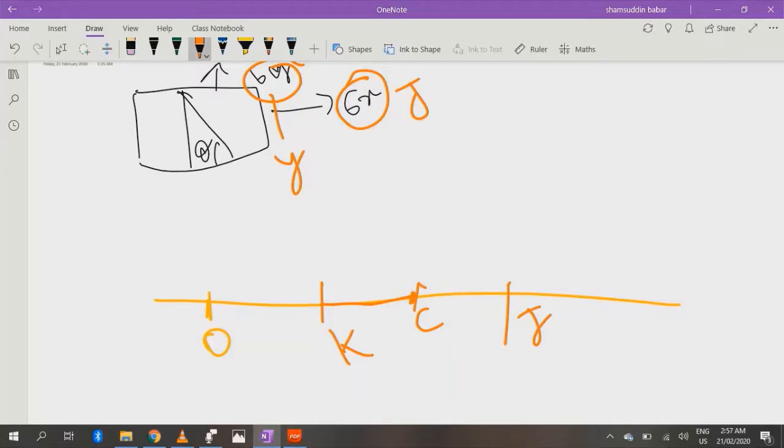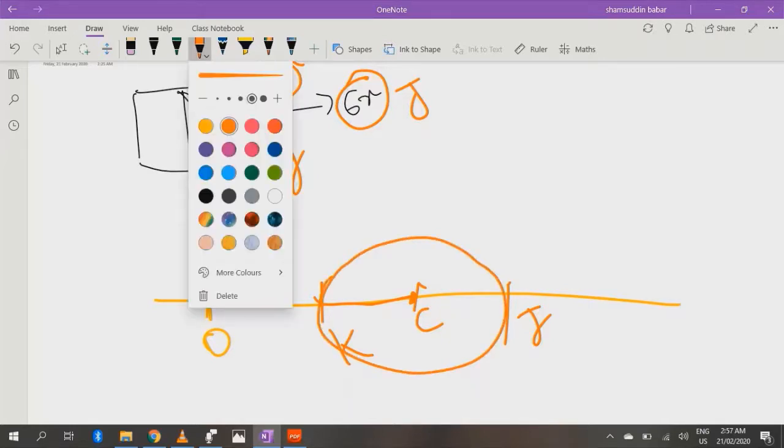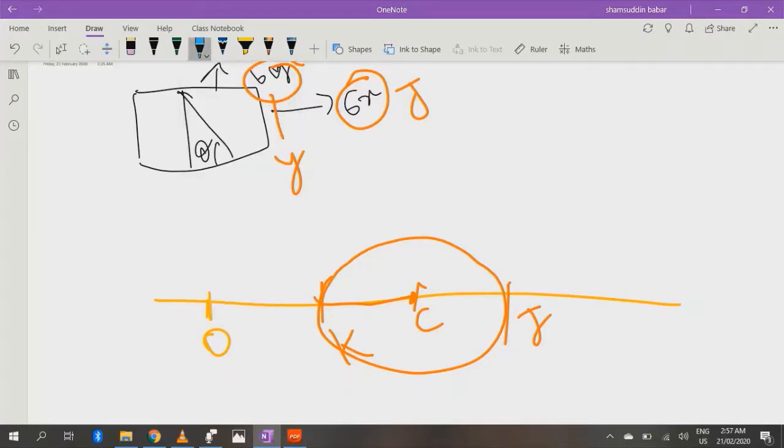C is the center. Place a compass with one point at C, and we can draw this Mohr circle. Now with this Mohr circle, we can draw a line at an angle of 2 theta from the line CO in the clockwise direction, and the point is P. After you have point P, drop a perpendicular to line CO.